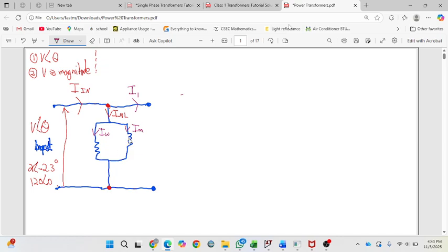magnetizing losses aren't dissipated in the circuit. You don't lose any reactive power. That doesn't exist. You only lose real power, which is power across a resistor. This is an inductor. So when you're doing your losses calculations, you do not include any inductor losses, because this is energy put into generating the magnetic field. That is it. If you switch off the circuit, that magnetic field just goes back. It will just shrink back down. So the energy isn't really lost, it's just stored in a different form, which is the magnetic field, right?